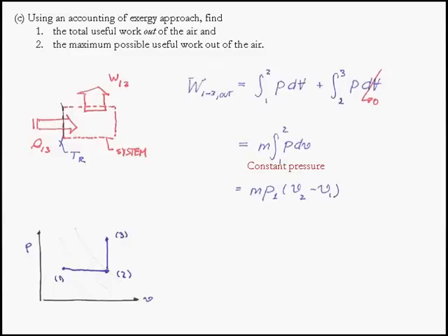So remember, we're dealing with an ideal gas with constant specific heats here. So far we've been using steam quite a bit. We've been using the steam tables or other things to find our properties. I do not find V using property tables for an ideal gas with constant specific heats, okay? Or even an ideal gas with non-constant specific heats. I use good old PV equals RT, and I solve that for V. So that's how I find V here. I have to calculate it.